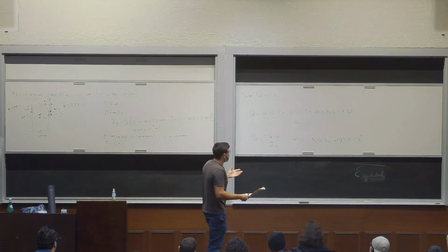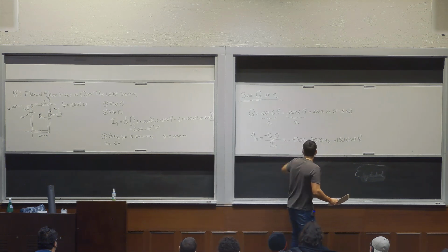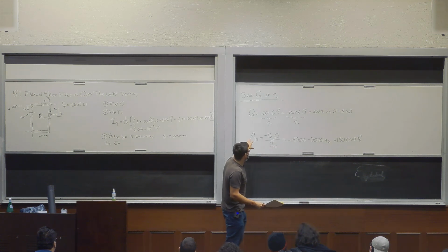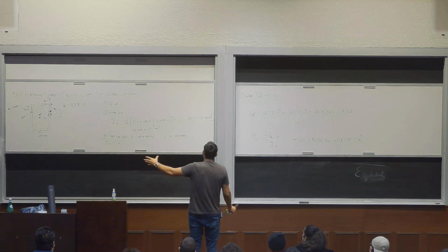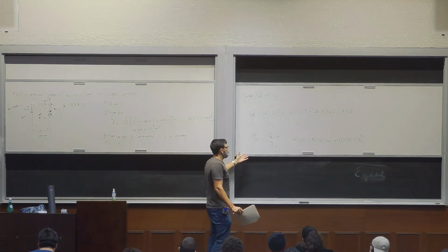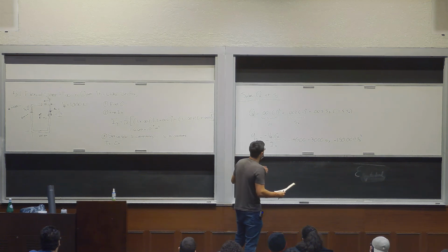And from these equations, again, you can plug in whatever value you want for S and find the shear flow, then divide by the thickness, which in this case is always constant, 0.002. Then you can find the shear stress. Okay, so just keep that in mind. We're not going to do it for this problem, but you could do that if you were asked to.